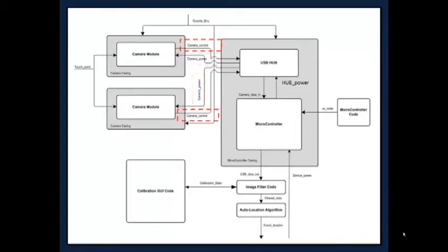The camera control signal is an I2C interface with a signal high of 2 to 2.8 volts, signal low of 0 to 0.3 volts. The camera data in is a control signal that is compiled information from all present cameras. It is also an I2C interface with a signal high of 2 volts to 2.8 volts and a signal low of 0 to 0.3 volts.